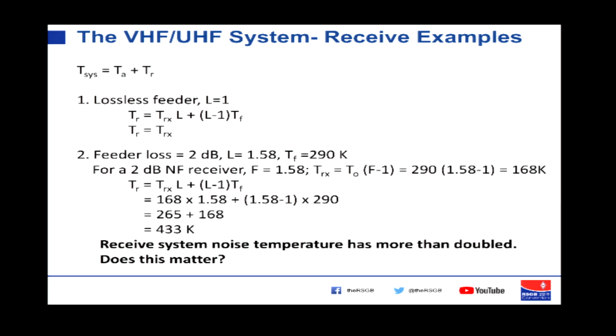And that is happening for two reasons. One, the feeder that you've connected has some loss, so you lose power, but also because I've assumed that the feeder is sitting at roughly room temperature, 290 K, and therefore being a lossy element, it generates some more noise and makes the performance worse.